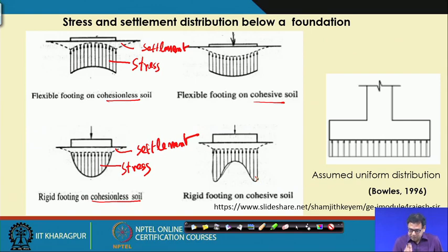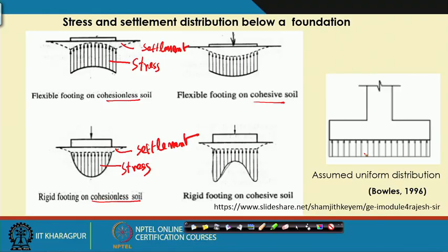But when we do the analysis, we assume uniform stress for all kinds of foundation resting on any kind of soil. It is true for uniform stress distribution if the foundation is flexible, but for the rigid foundation it is different, but in that case also we assume uniform stress distribution. So, these are some information you should remember when you solve any shallow foundation problem.